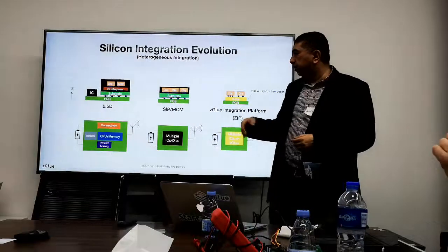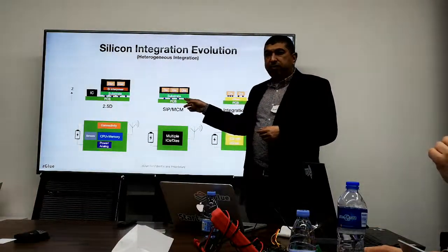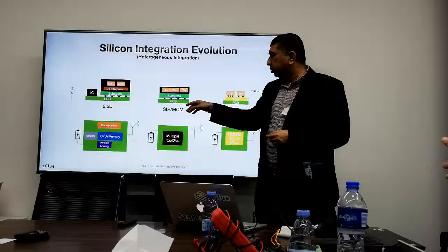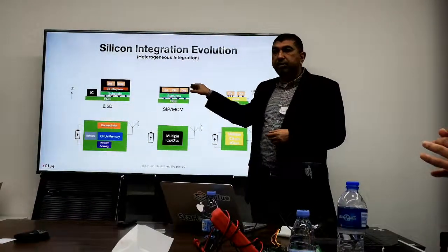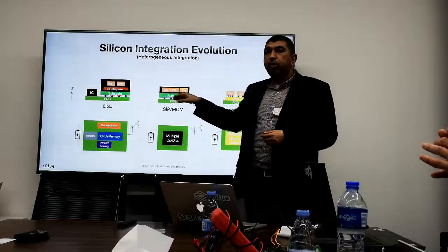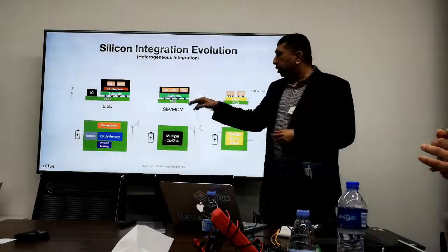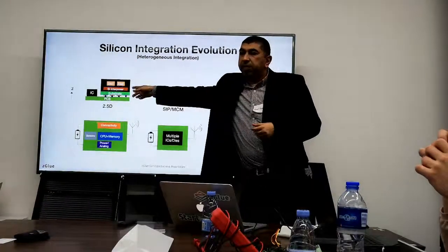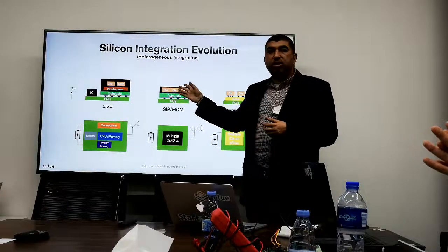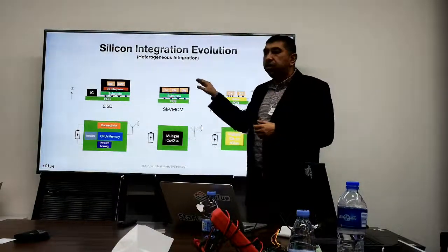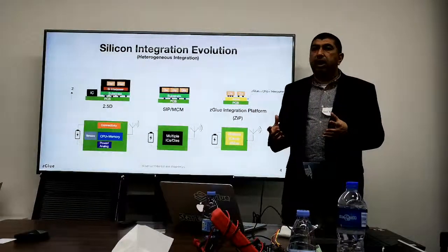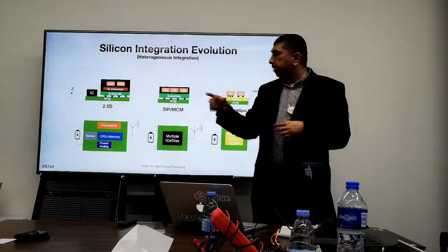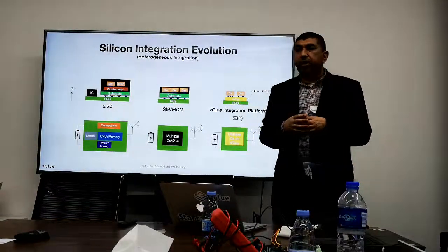That's the direction. There's a lower cost variation of it that is called system in package or multi-chip modules. That's where you take multiple dies and then you put them onto a fine pitch substrate. You can make the substrate really, really fine pitch, but its cost starts going up. So for cost considerations, usually these are the type of solutions that are available if you want to make a really small module. This is the direction that people have done.